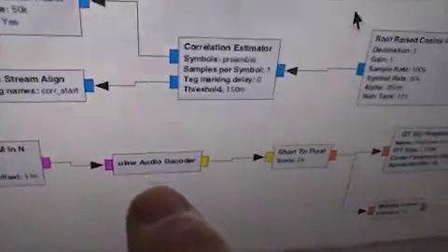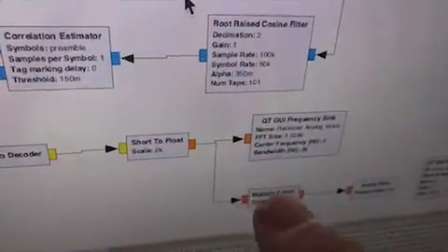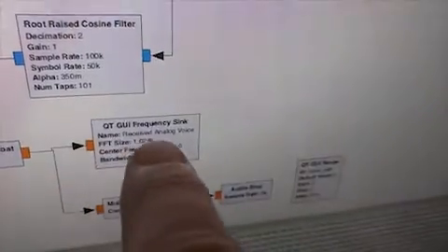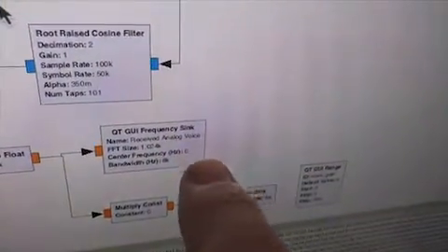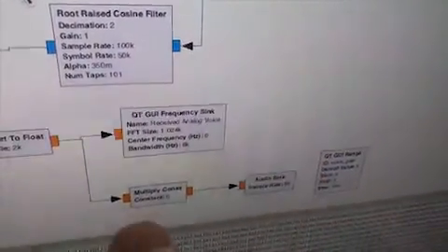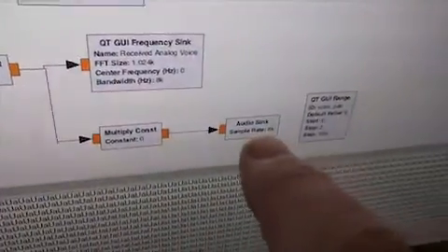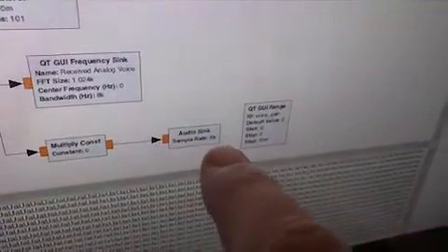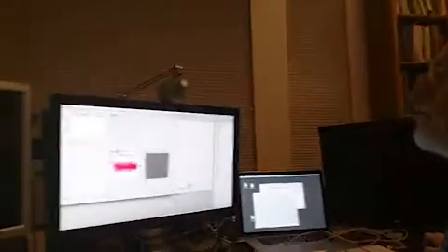Now we're down to the mu-law decoder, some arithmetic conversion. We get to peek at it again with another spectrum analyzer if we want to look at the received audio. And then into the audio sink where it plays out through the speakers. And if we're actually transmitting, this would possibly work. Let's try it. Right now we're getting underflows like crazy, though, so we better start and stop this one again.